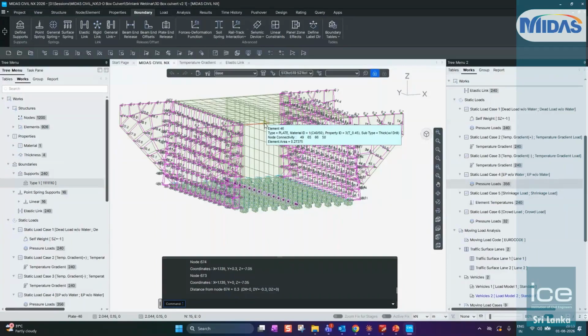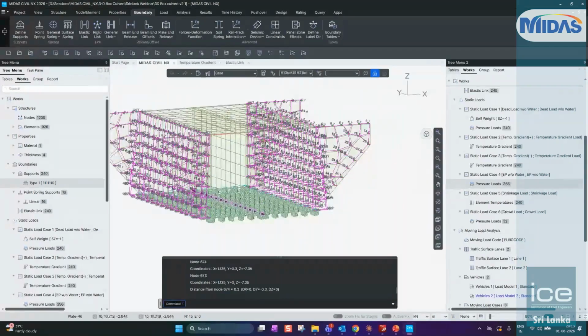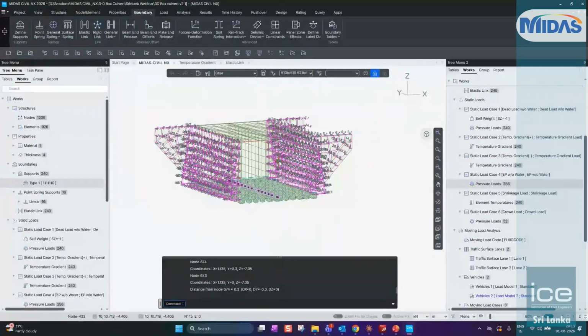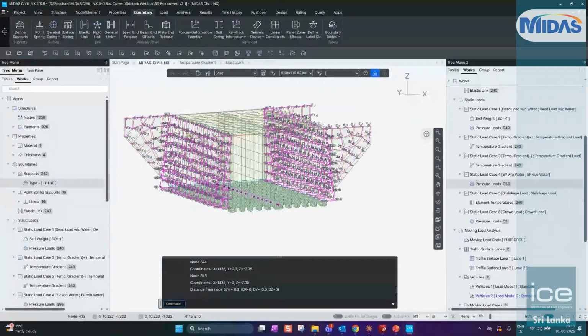And if that is the case, then you must always model the difference of soil pressures on the two sides, and also try to see how much sliding you are getting, because sliding will not be possible on the other side of the wall. You'll have a huge quantity or volume of soil to resist that in passive resistance, right? So exactly sliding will not happen, but if there is any difference in the soil pressures, then we must account for it to locally design these walls, okay, for the local design of these wall elements. Okay, I hope I'm clear on this.